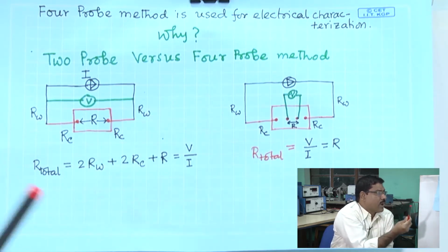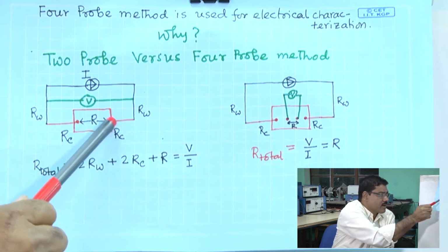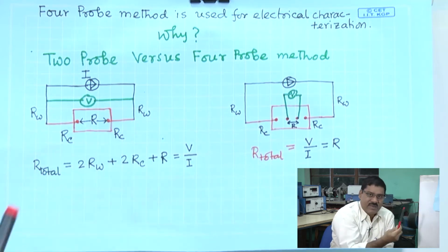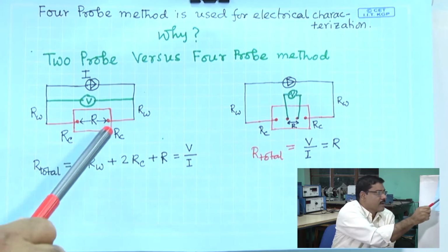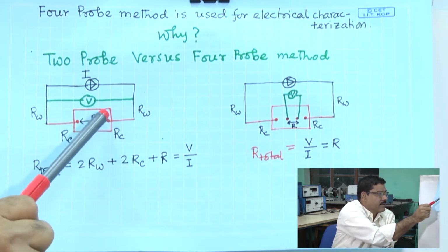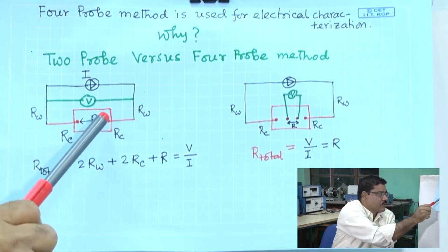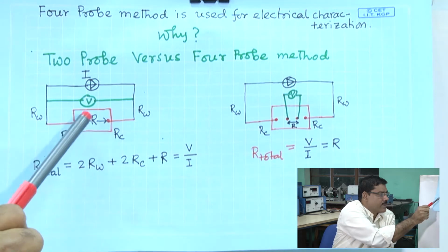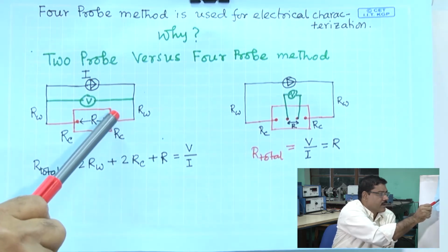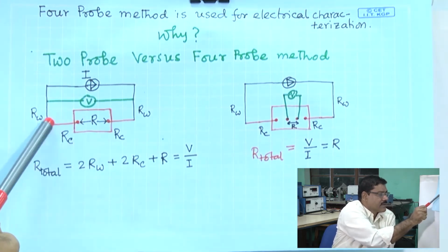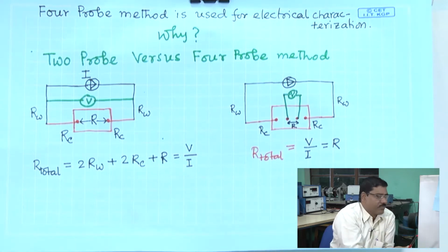With some wire you have to make contact, either using silver paste or whatever way. You have to make an electrical connection with this sample; from these 2 points, one can also solder.